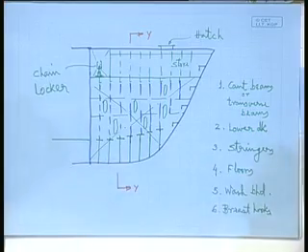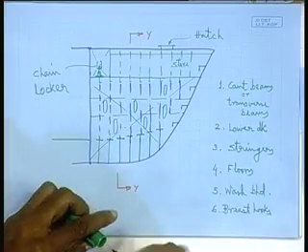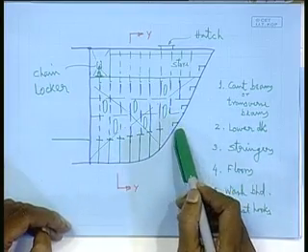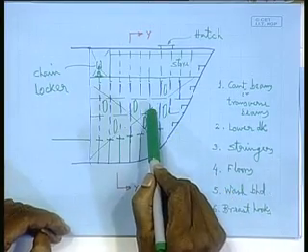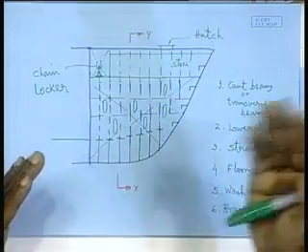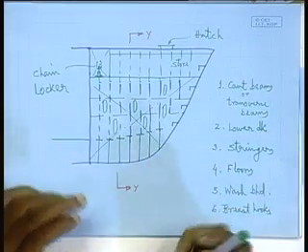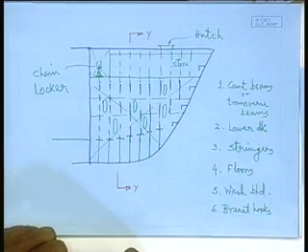So that is the somewhat elaborate construction arrangement for the forward end. The whole idea is to make it locally stronger by floors, by stringers, by breast hooks, the centerline bulkhead, and then the deck beams or cant beams. Okay.